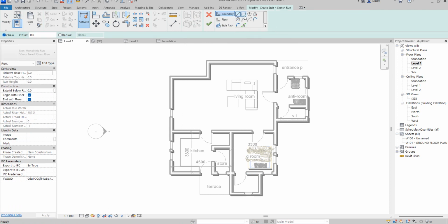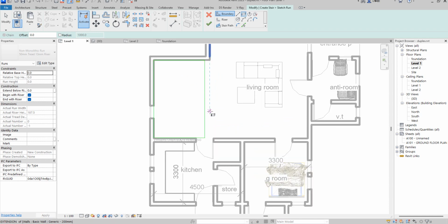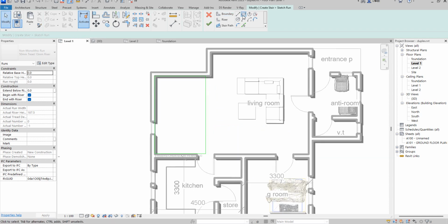So all you need to do is to click on create. So after you click on create, the boundary, I just want it to flow all through here. So I'm going to put it here. Anything that I want, I will later adjust it for my own taste. So now I have that. So the next thing, I still select this one, and this time around I'm going to say offset 900. I'm supposed to use minus, so I'm going to press minus because I want it to cut inward. So say minus 900, which is fine for me.